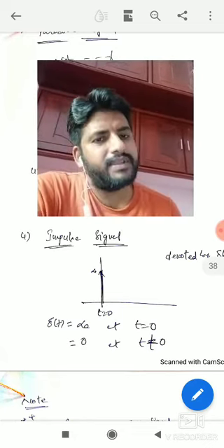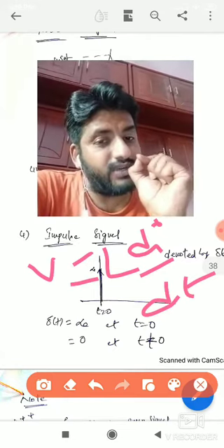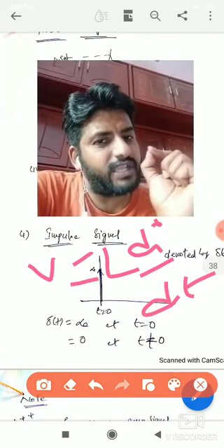First assume that it allows the current suddenly, that means in 0 time. So the time should be very less. If the time is less, my voltage should be very high. That means if the time is 0, my voltage is infinity. If infinite voltage enters the inductor, it will get damaged.